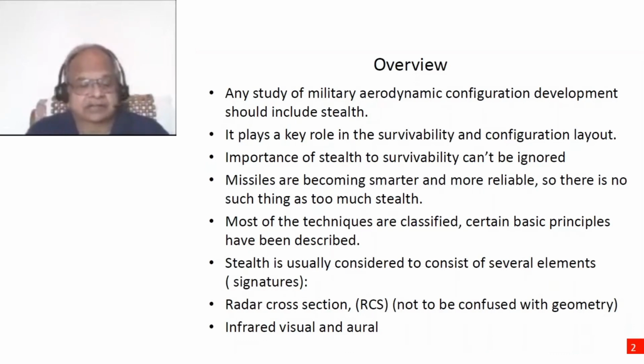And because stealth characteristics cannot be an add-on after the aircraft has been designed, it also impacts the configuration development right from the beginning. So the point is, if they want to have characteristics of stealth built into an aircraft, it has to come right from the beginning, from scratch. It has to be designed like that. And the importance of stealth cannot be overstressed because it directly impacts the survivability of the aircraft and the pilot within that.